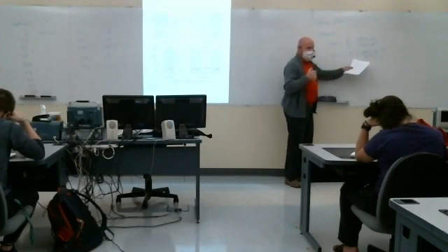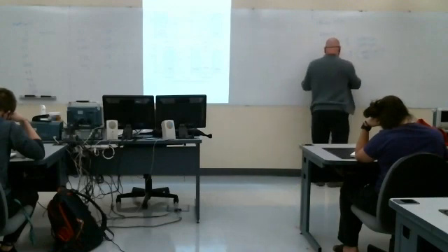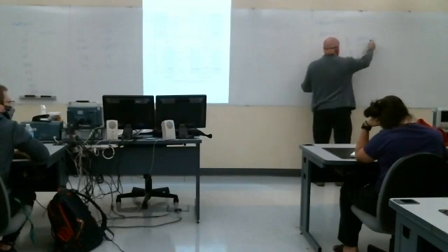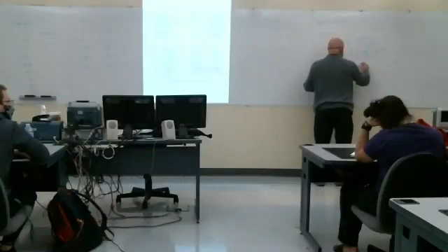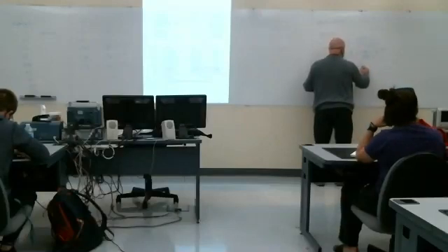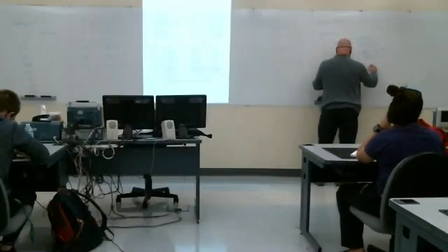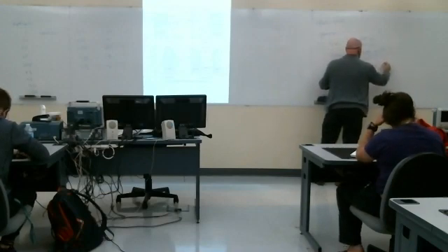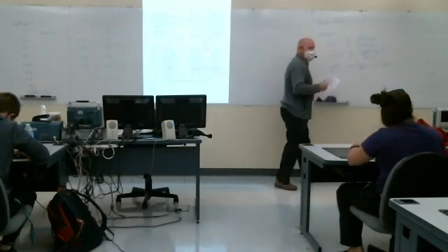You can plot it in dB, just 20 log of this. The phase response would be the imaginary part over the real part, so it'd be 2 omega over 16,000, and then minus the angle of the denominator, which is omega over 1,000. And pretty easy to plot that